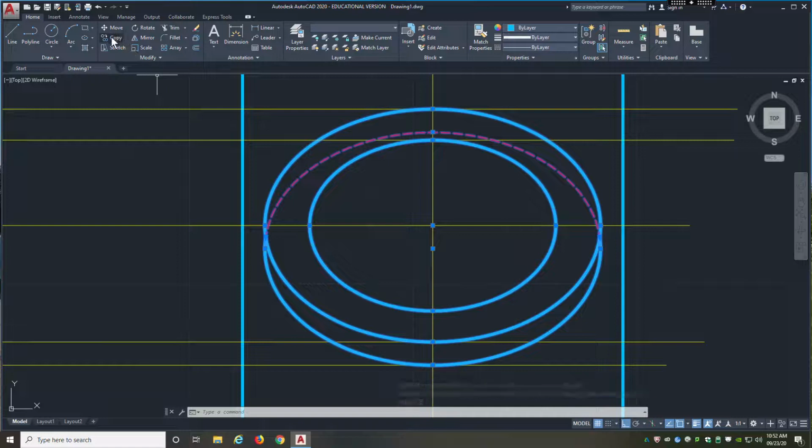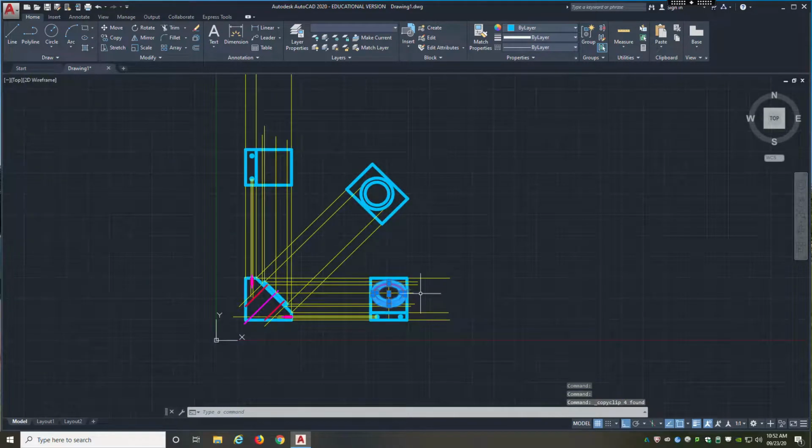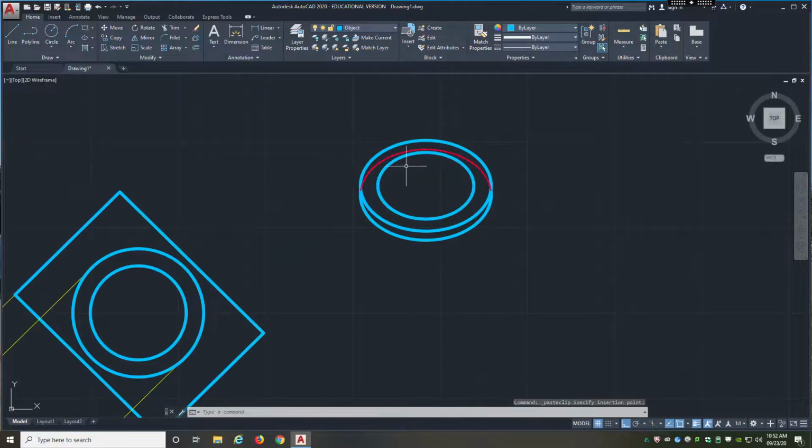and I'll do it this way. I'm going to Control C to copy that information, and I'm going to Control V to bring it out and left click and set it into space. Once I do that, I'm going to select it one more time, and I'm going to rotate based off of the center point. Make sure you get the right center point, should be the top one.